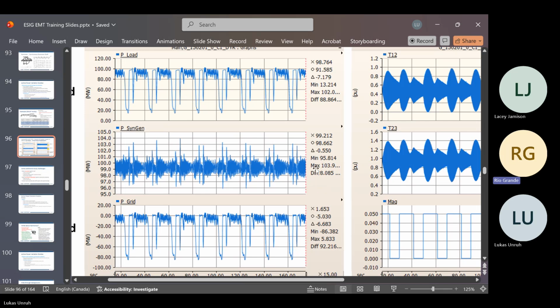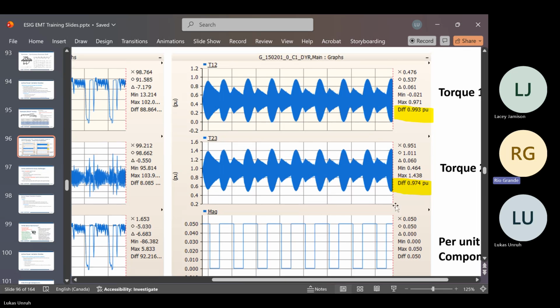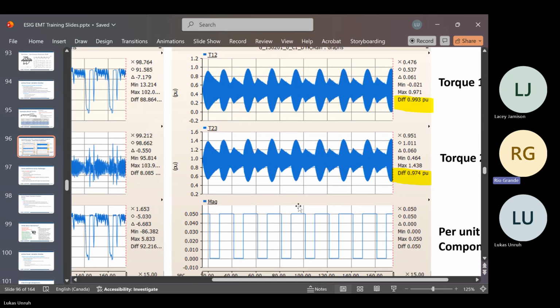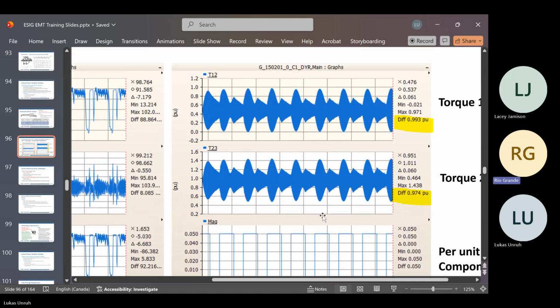And you can see that there's a lot of harmonic content showing up at the synchronous generator, and some of that is that dangerous 12 hertz. On the right, we've plotted the torque on the various generator shaft sections, and you can see where that 12 hertz component is being put in and taken out, according to this plot on the bottom. When we put it in, we see the torque growing up to near 1 per unit, and then if we take it out, it goes down and settles again, and then comes and goes as we take that component in and out.